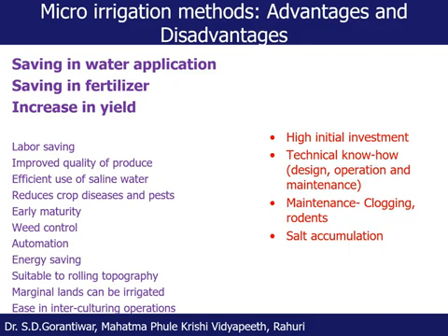But in case of the drip irrigation system, as we can maintain the water at low tension or at high water content, even if there is saline water, and if the salts are accumulated in the root zone up to a certain level, of course, the roots won't find difficulty in extracting that water, because water tension is low in the root zone, and therefore we can use the saline water efficiently as compared to other irrigation methods wherein the irrigation interval is large. Again, this has to do with the frequent application of water, by which we can maintain the water content in the root zone at low tension or at high content.